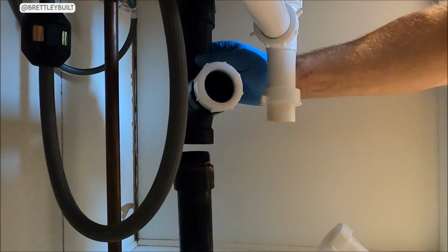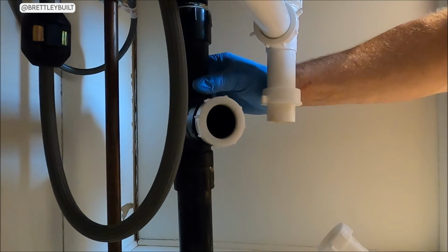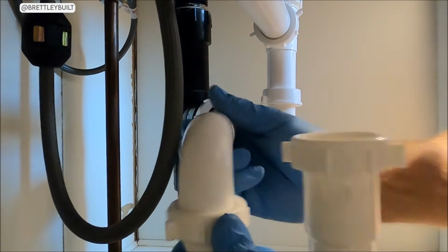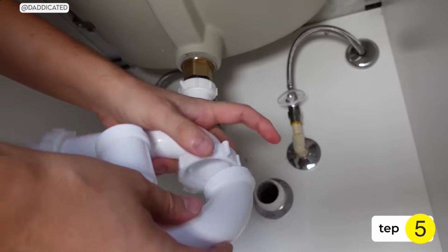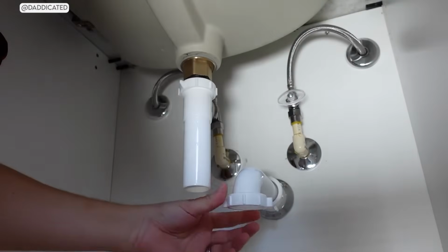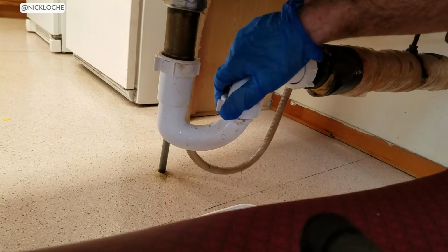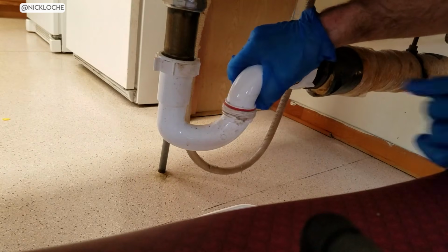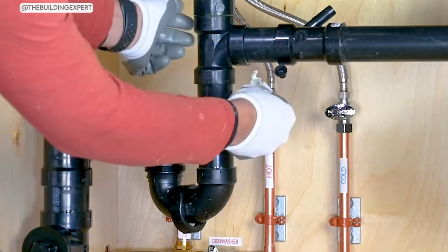However, if the wall behind the sink already has a drain stub and vent, the swap is much simpler. You would remove the old S-trap, install a new P-trap assembly using 1.5-inch pipe for a bathroom sink or 2-inch pipe for a kitchen sink, and connect the trap arm to the wall stub.